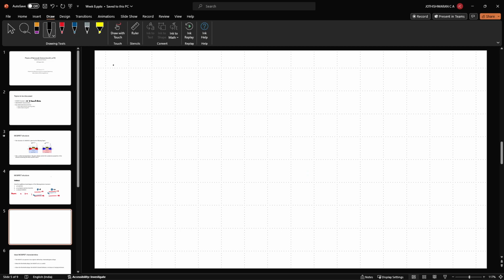Now, upon forming the junction, this is part A being continued. Upon forming the junction at equilibrium, which we have more or less discussed in our earlier weeks' sessions, where we were talking about the drain source channel system, whatever we considered there is equally valid here. At equilibrium, the Fermi level across the device has to be uniform. That implies that the probability of finding electrons at any given energy should be the same across the entirety of the device. That is the equilibrium condition.